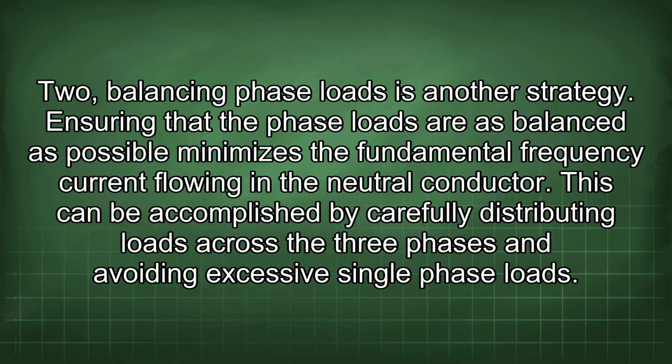2. Balancing phase loads is another strategy. Ensuring that the phase loads are as balanced as possible minimizes the fundamental frequency current flowing in the neutral conductor. This can be accomplished by carefully distributing loads across the three phases and avoiding excessive single-phase loads.